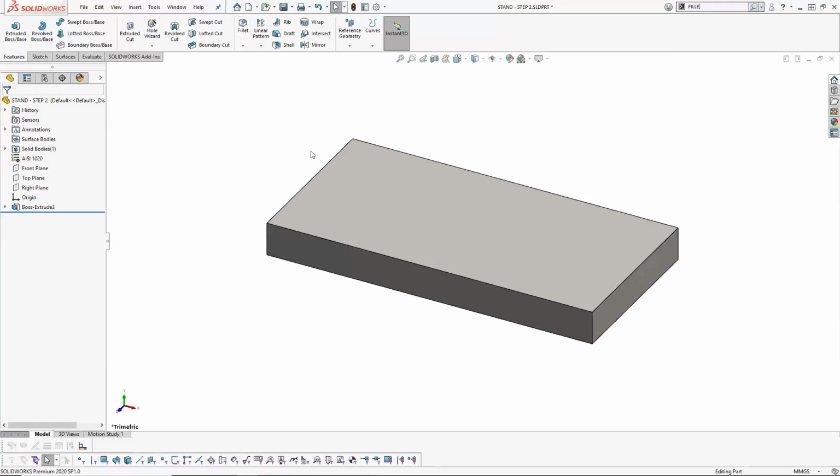And this is super helpful. Like if I wanted to do chamfers, I don't see the chamfer command anywhere in here. So if I come in and say chamfer and hit the button, it will just run the chamfer. But if I click on the eyeball, it'll come over here and say it's in here. So I can hit this down arrow and there's my chamfer command. So hopefully that helps you with the search here.